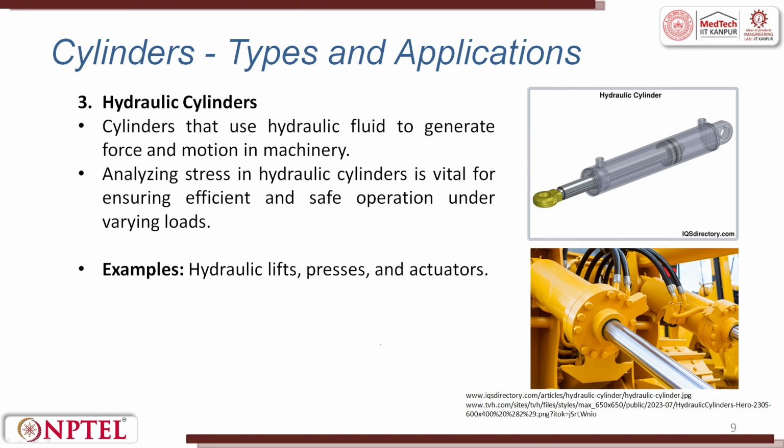There are hydraulic systems. For example, this hydraulic cylinder is used in the stamping process. In stamping, what we do is we keep a plate and then we have a die. So, we have a workpiece which is resting on a die. Then we have a punch which comes from a certain distance. It pierces the sheet and then enters into the die, thus making a hole on the surface.